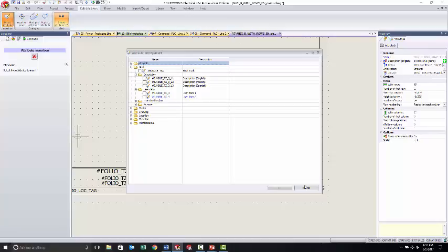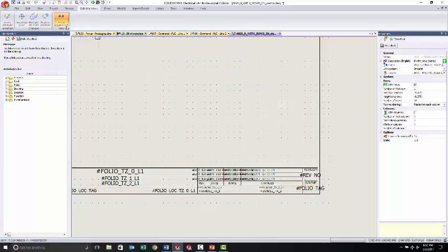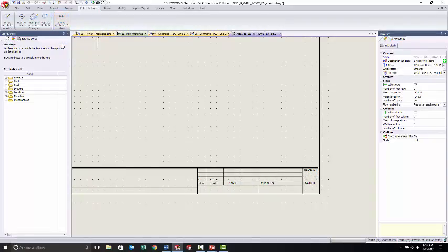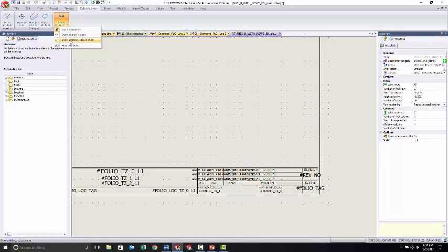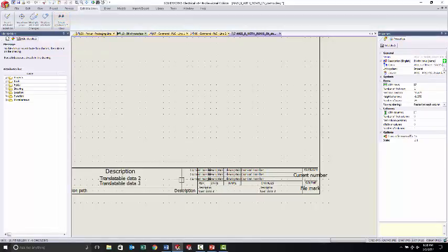What they have added here in 2017 is this drop-down called Show Attribute. What it allows you to do is, one, when you are working strictly in the graphics, you can turn off the attributes. Hide them all. Work on the graphics only. This works in both title blocks and in symbols. I can turn off everything and work on just the graphics. When I'm done with the graphics, I can turn the attributes back on. But when I turn them back on, they're still foreign to me. I can now hit Show Attribute Description, and it tells me exactly what it is.